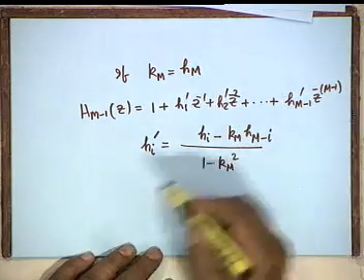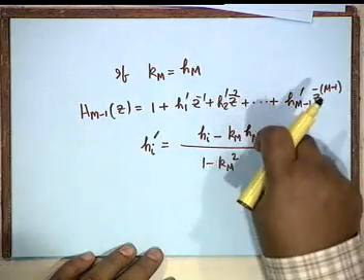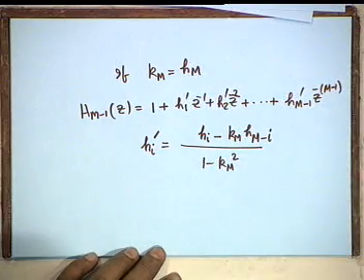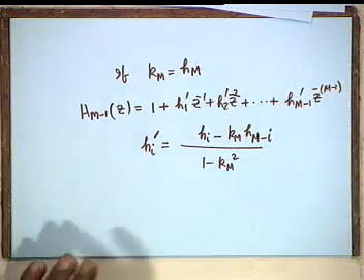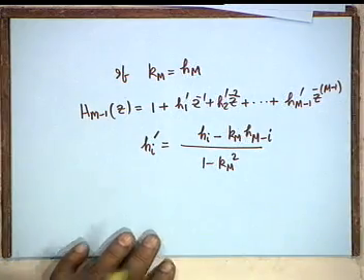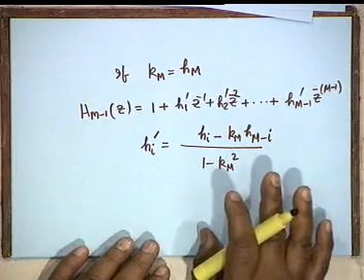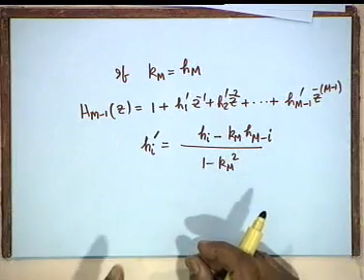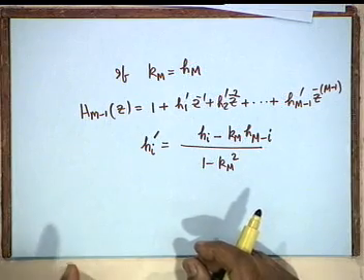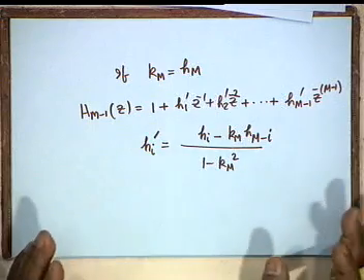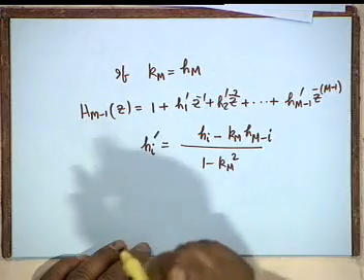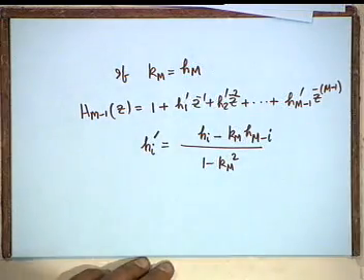Don't we know this relationship? It is the same relationship as used for IIR all pass designs. Okay? You see the elegance of the method. Okay? So it is the same relationship. Once you know this, it is applicable for FIR, it is applicable for IIR also. In IIR it is only all pass, in FIR it is an arbitrary transfer function except Km equal to 1.